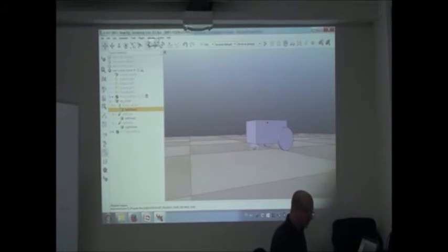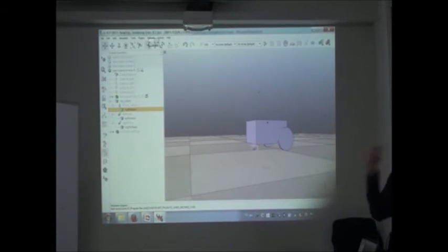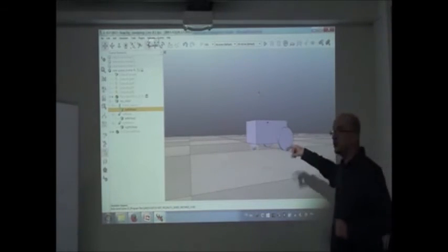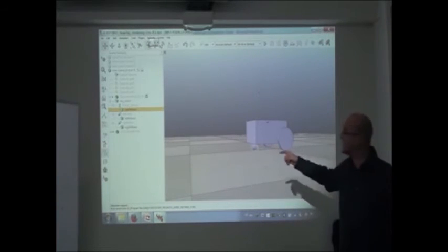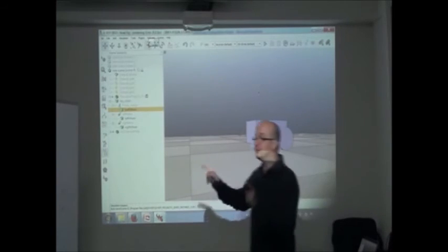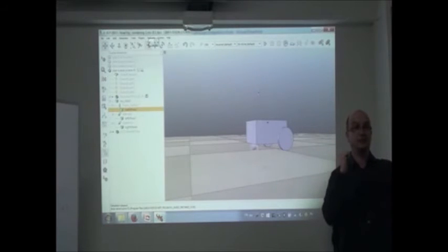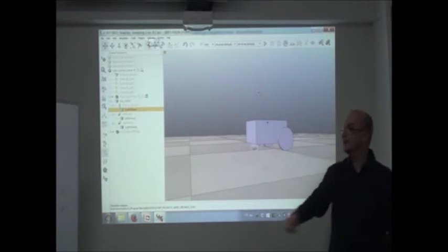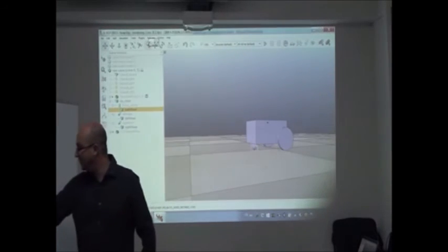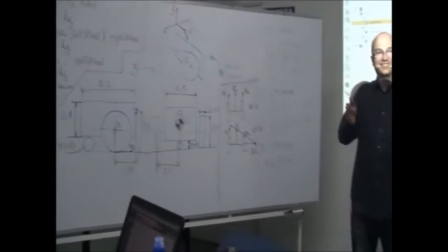So now we have a fully functional robot. We need to put some behavior in it, right? We did put some behavior, not in the script, but directly a constant. We put a constant of velocity into each model right now. So we put the same velocity left and right, it goes front. Now if I put the velocity on the left wheel, let's say 10 degrees per second, and minus 10 degrees per second, what will happen? It will rotate at the point. The instantaneous center of rotation will be here. If I put 10 and 5, what will the robot do? It will go like that.